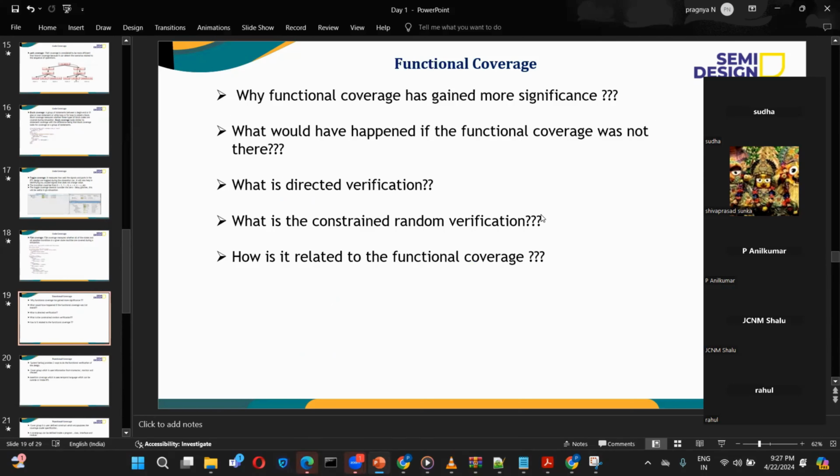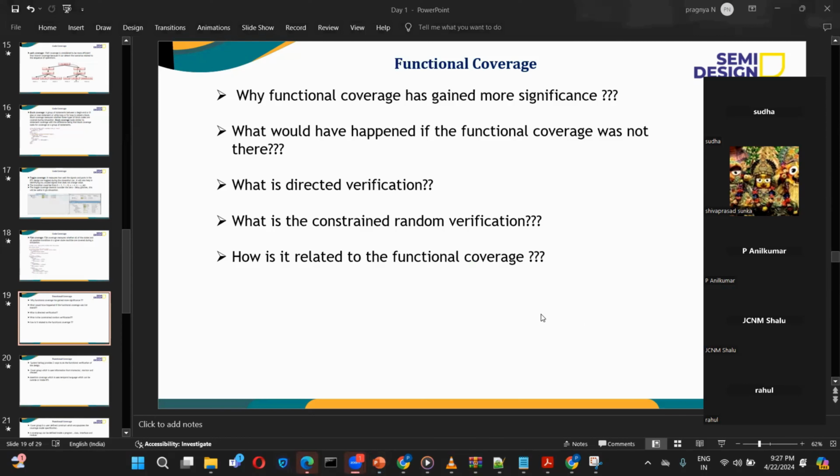So how can we write this code coverage? Like, will the tool detect this automatically? Yes, the tool will automatically give the code coverage report. Based on the code coverage report, if you want to make any changes, for example, as I explained for toggle coverage, we need to do that analysis and add the exclusions.